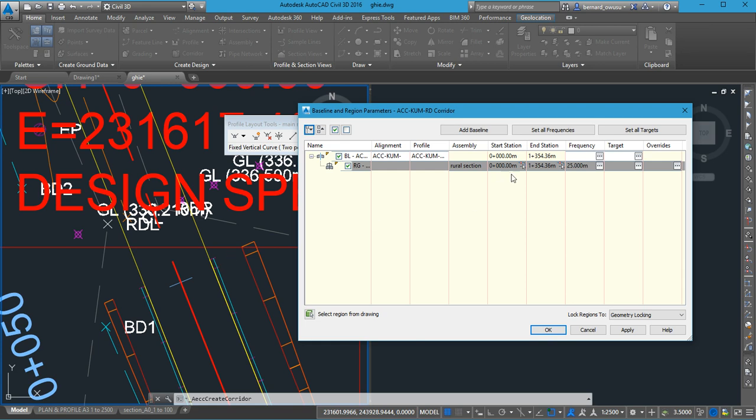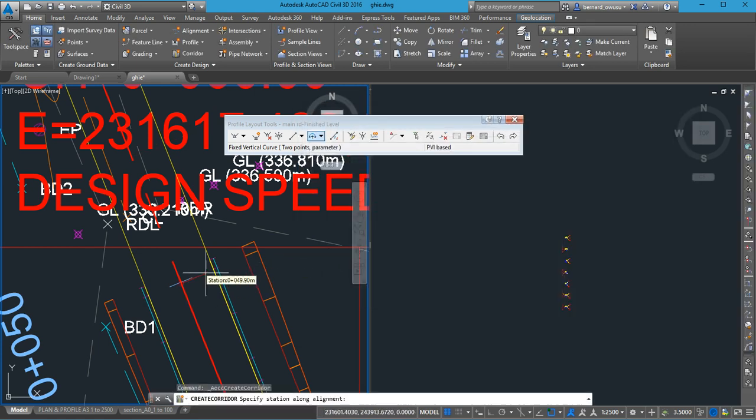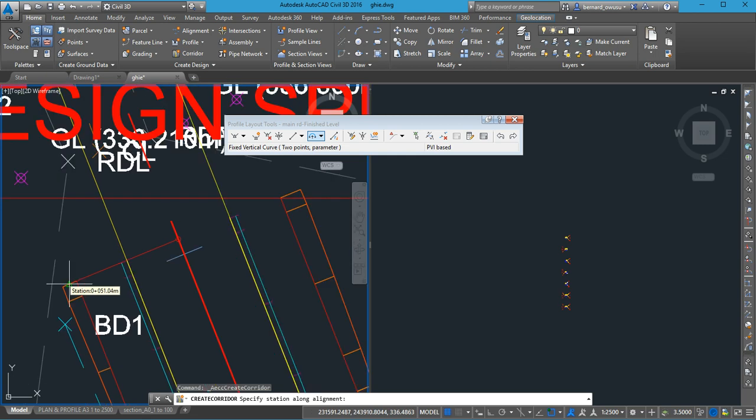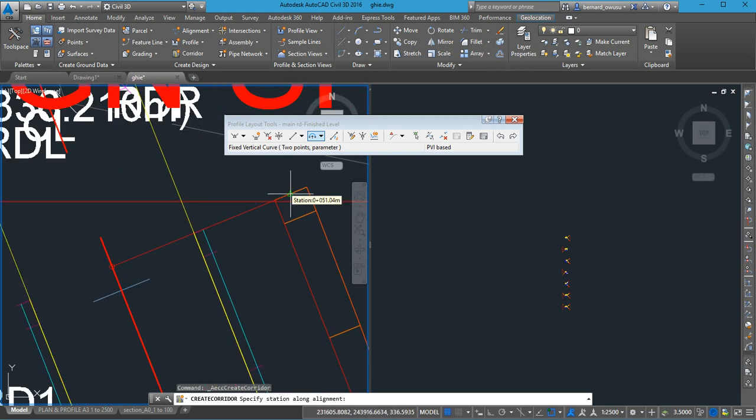So you please come here. Please watch. If you know the chainage, I can click inside and type. But I don't know the value of the chainage. So can you see that there's something like a cursor after the number with like a star on it? Click on that one. And you see that it will bring you to the plan for you to select where you want to start from. I'll click any of these where the corridor is ending.